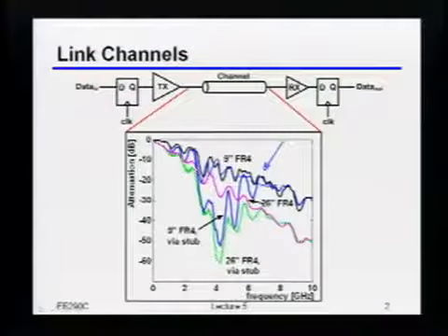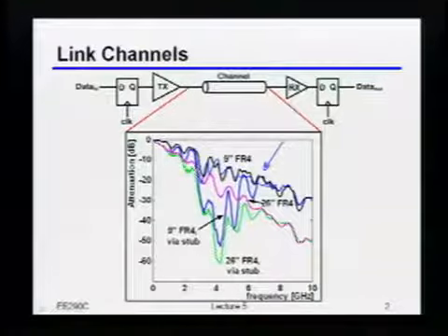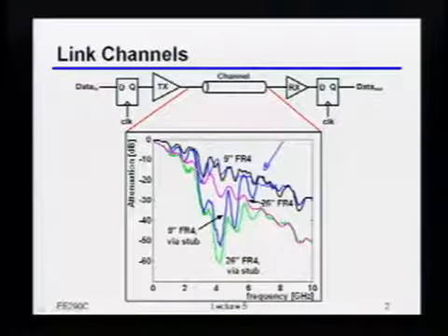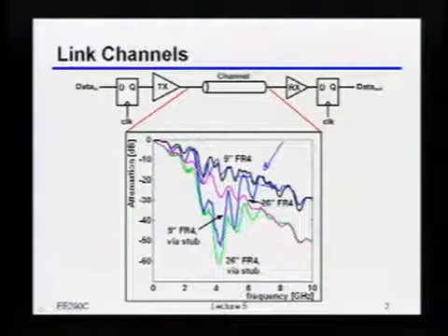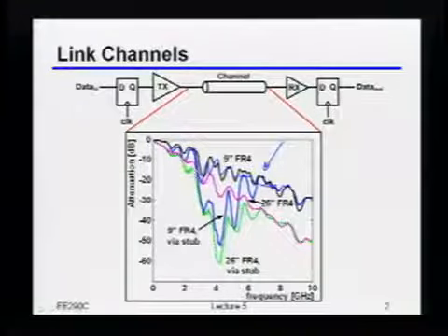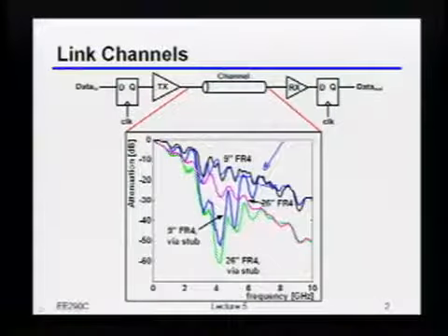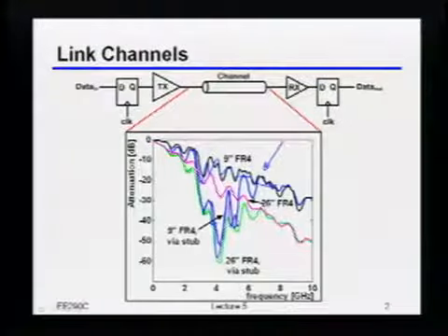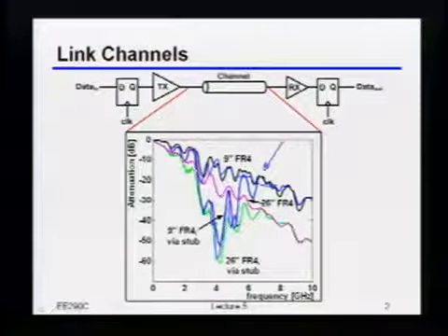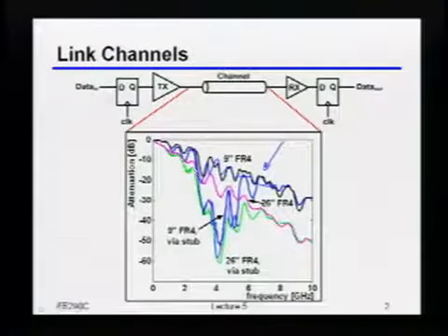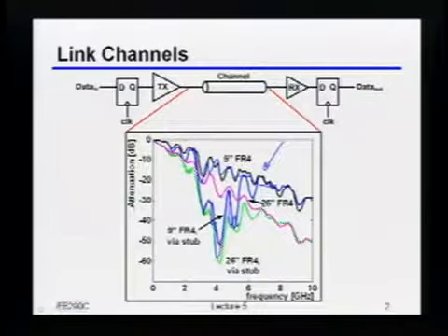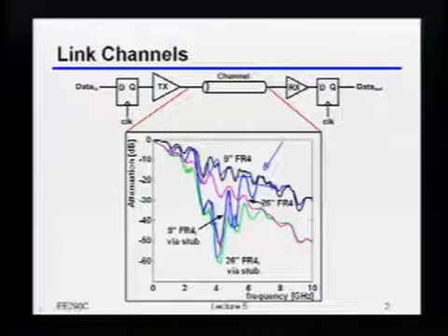So if you wanted to build an analog circuit that was the inverse of that, how many poles and zeros would you need? Lots. Yeah, a lot. I don't know, but a lot, right? Even worse than that, if you had some deep notch like this, now you have to really build some very funky analog circuit, which, by the way, the Q of that notch might even be higher than the Q of what you can get with your on-chip components.